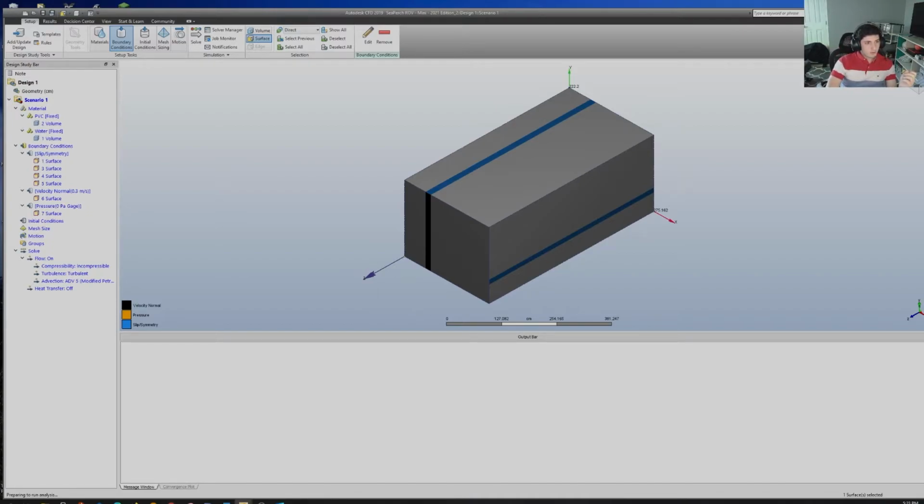So looking at the hydrodynamics of how the water flows around your design is the best way to improve your bot's efficiency and speed, because it allows you to minimize the drag and reduce turbulence. Minimizing drag and reducing turbulence is very key for elevating the performance of your bot and making it more efficient. And it's much easier to improve that than by increasing the thrust, since we can't change the type of motors that we're using, and you can't really change the propellers unless you can find a viable alternative.